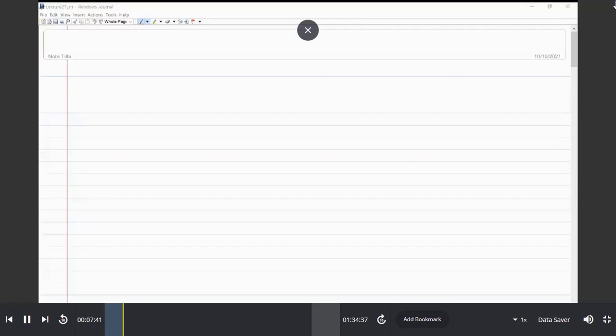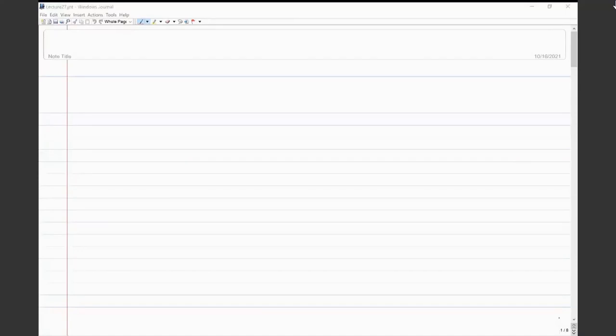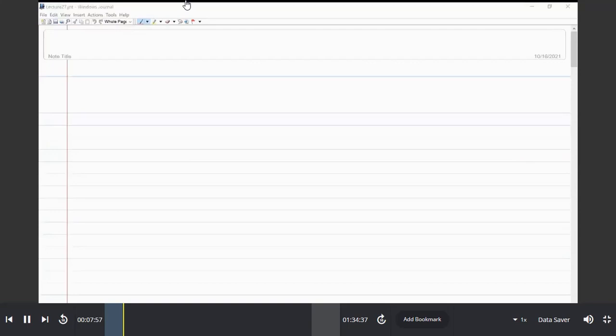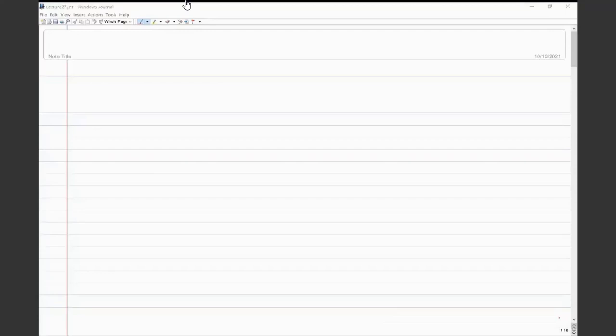Sir, last class we did the Rayleigh proportional damping model. There, phi i transpose C phi i we have written as 2 xi omega n i. We have not given the proof, but that is how it comes. If phi i is normalized with respect to the mass matrix, then it is like a single degree of freedom system.